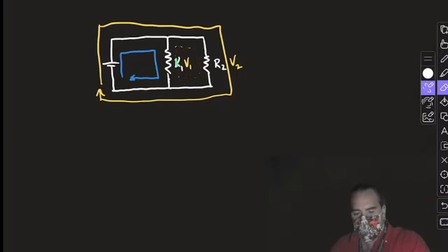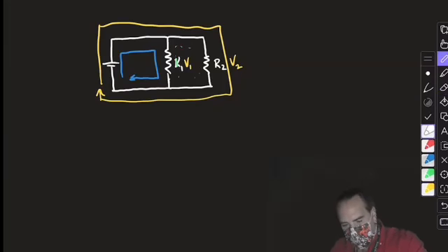If I use just the yellow loop and the blue loop, I've drawn them specifically in a way to ensure that the voltage drops from our resistors are actually negative voltages. Because if we just look at this picture, we know that that has to be the direction of the currents. We'll get into something a little more complicated later in the semester, but not now. So I'm going to do the yellow current first.